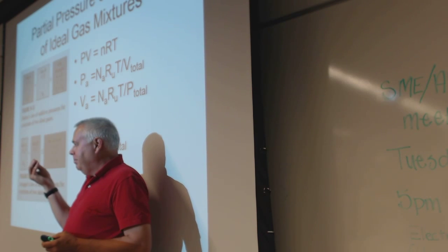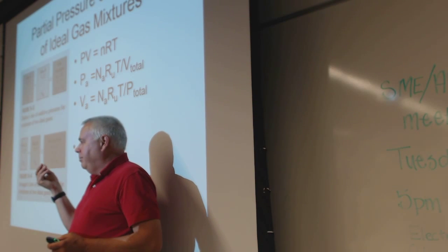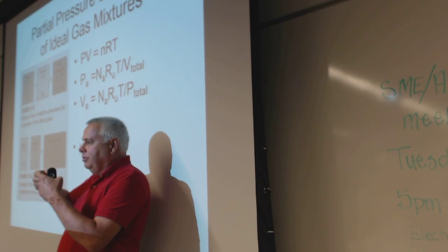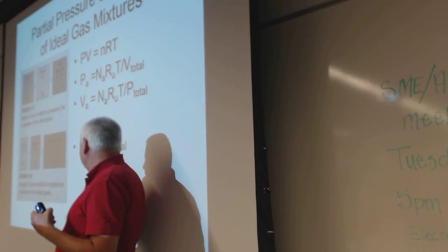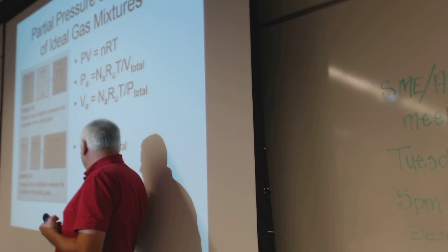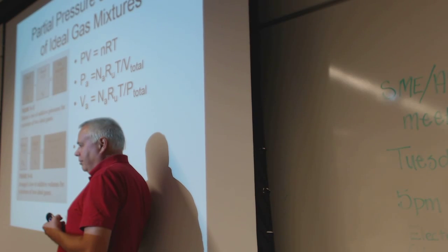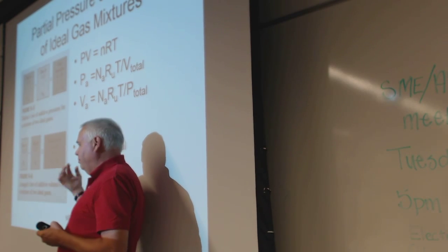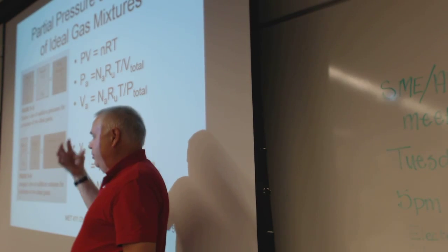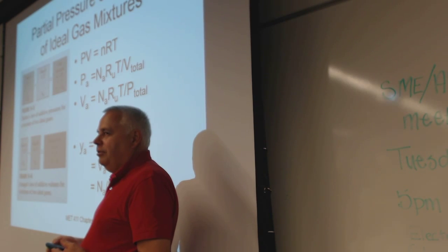it's the saturation temperature for the pressure of the water vapor. You found the saturation temperature for the partial pressure of the water. If you know the partial pressure, then you know how much mass of water is in the air. You know the number of moles per total, and then you can back into exactly how much mass of water is in it by temperature. Drop the temperature till it makes water. That's the dew point. That's the temperature at which water condenses.